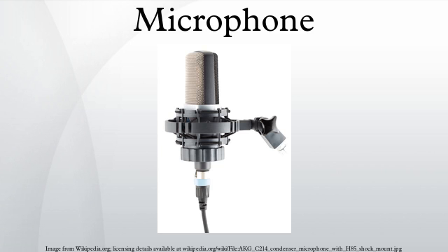Many noise-cancelling microphones combine signals received from two diaphragms that are in opposite electrical polarity or are processed electronically. In dual diaphragm designs, the main diaphragm is mounted closest to the intended source and the second is positioned farther away from the source so that it can pick up environmental sounds to be subtracted from the main diaphragm's signal. After the two signals have been combined, sounds other than the intended source are greatly reduced, substantially increasing intelligibility.